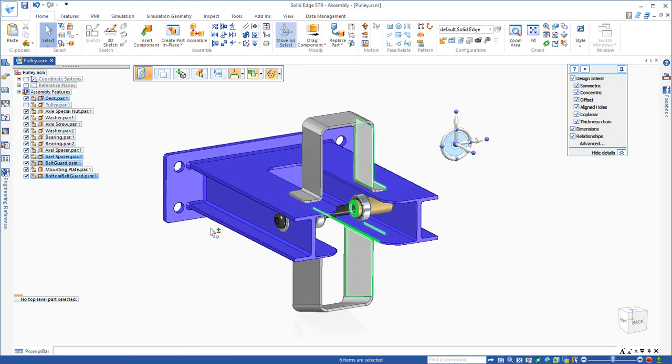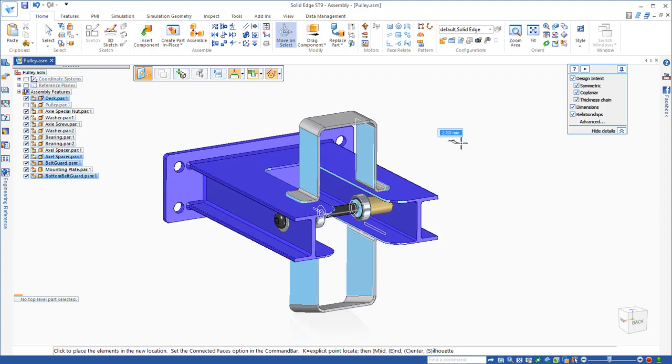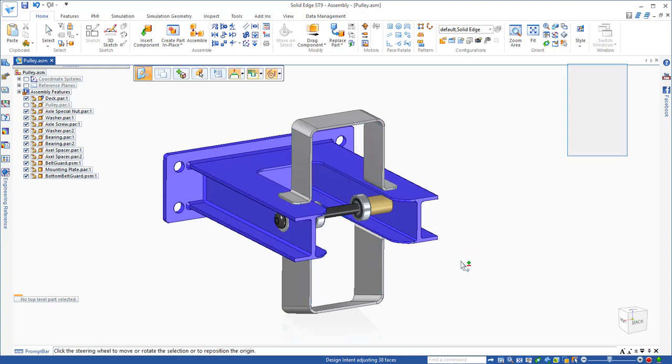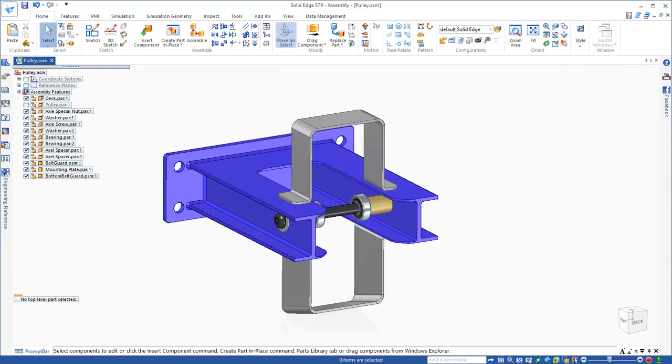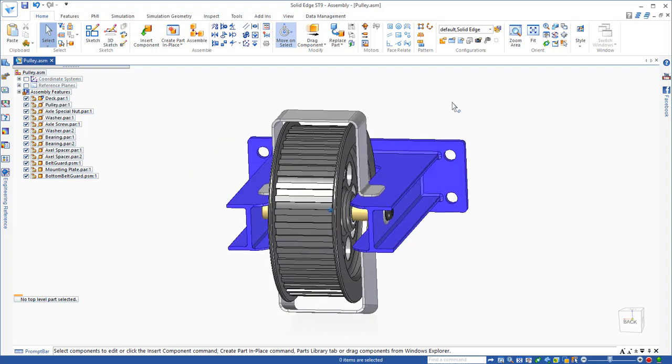Once those are selected, you can see there's 4 different parts. I'm modifying all 4 parts at the assembly level exactly like I did with the pulley, and I'm just going to go 10 millimeters again because it is going to stay symmetric. If the pulley had been synchronous to start with, I could have changed the pulley along with all of those parts at the same time.